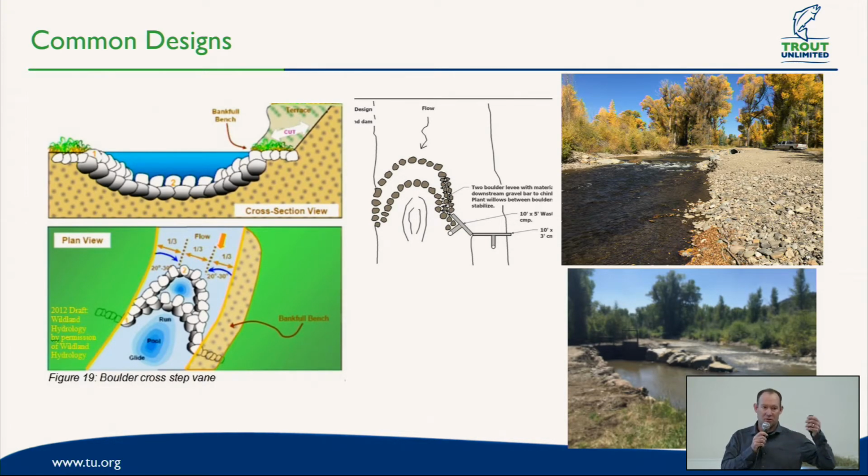You pull it open, say during high flow periods, and let that natural flow carry that sediment. Keep it moving through instead of depositing it right upstream. Then low flow, you can check that down and get it all into your ditch. And that can be placed down ditch somewhere at the head gate. It's site specific.